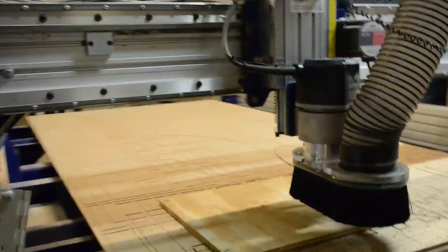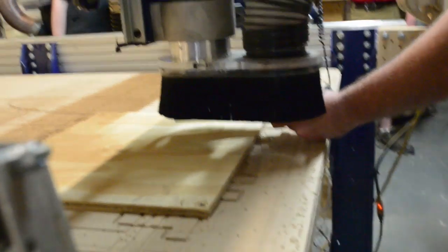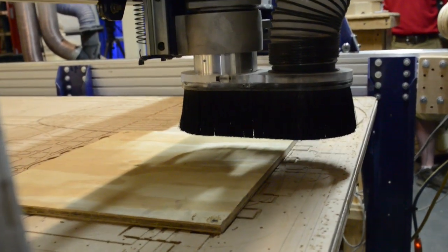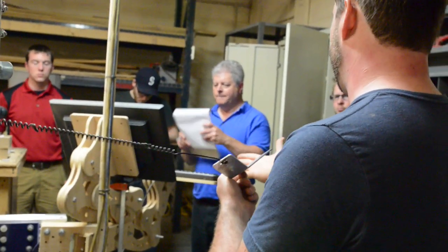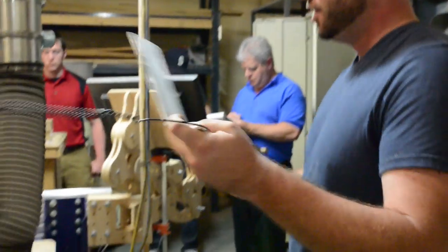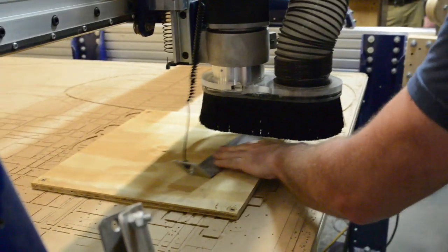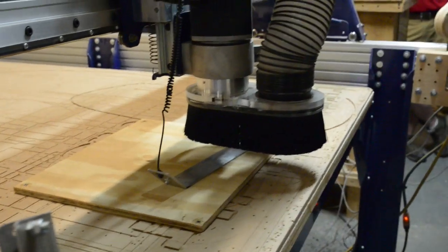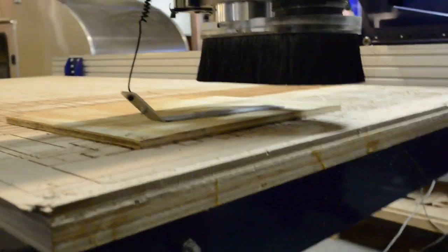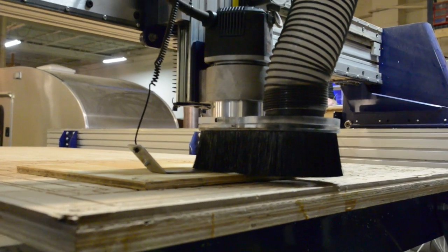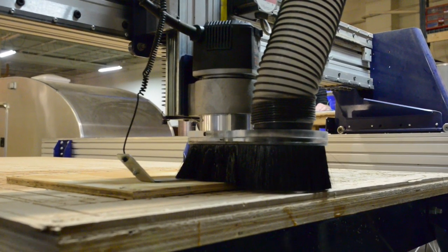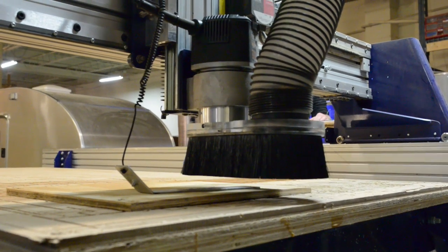If you actually watch, right here on the inputs, number 1 light should light up when I touch this to the bit. And that's what it does. The machine knows the exact thickness of this, so when it hits it, it'll automatically add this thickness to whatever it did, and now it'll zero it automatically. So all you've got to do, put it underneath it, press enter. Make sure you're going to touch it. It'll go down real slow, touch. Okay, it'll go up, and it'll come down even slower, just to dial it in perfectly.